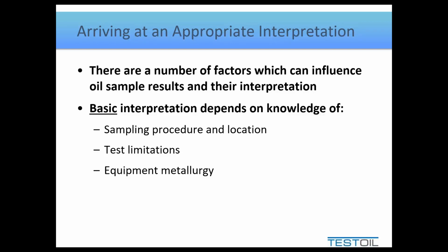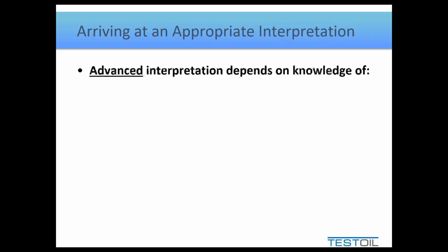So little things like this, you learn through experience, or at least learn by asking a lot of questions. The last thing we need to do is employ trending. Trending above all else will catch the kind of problems that we're looking for on an oil analysis report. Relying on alarms is going to be misleading at times and not come early enough. But the point is, a basic interpretation needs knowledge in at least these 4 areas, and this is something that labs do well. But to get to that advanced interpretation, you need a little bit more.